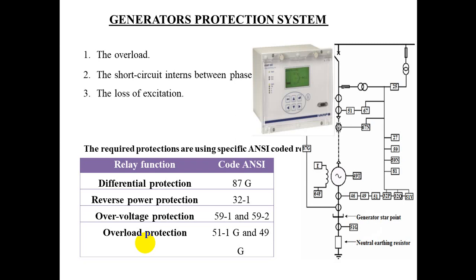Backup protection of generator. Backup protection should always be given in highly rated machines like the synchronous generator or alternator. If faults have not been cleared by the appropriate protection scheme, then backup protection relays should operate to clear the fault. Overcurrent relays are generally used for this purpose.